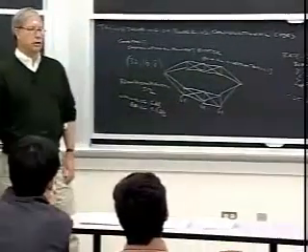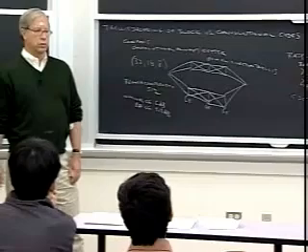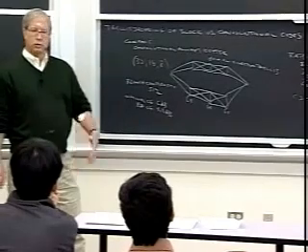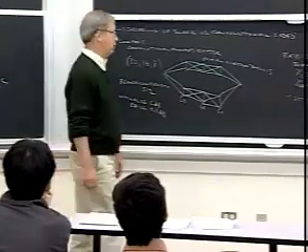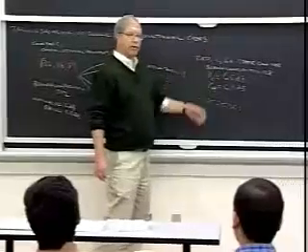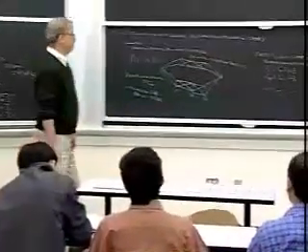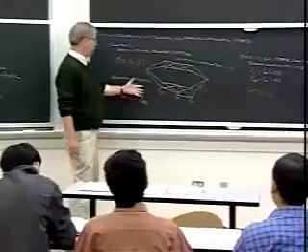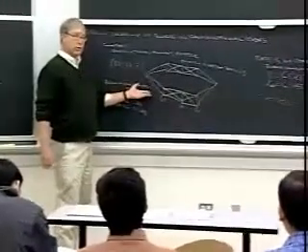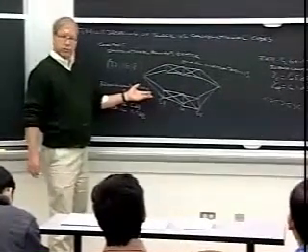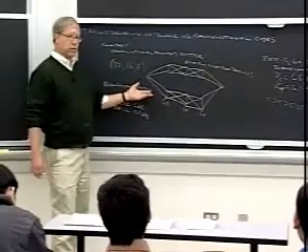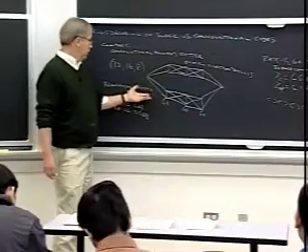With termination, you don't lose minimum distance, but you do lose rate. You have to put in some dummy information symbols, so the rate becomes less than 1/2. Nonetheless, as I believe I commented earlier, that's a good way to come up with good block codes: terminate a good convolutional code. If you choose the parameters right, you can come up with pretty good codes.